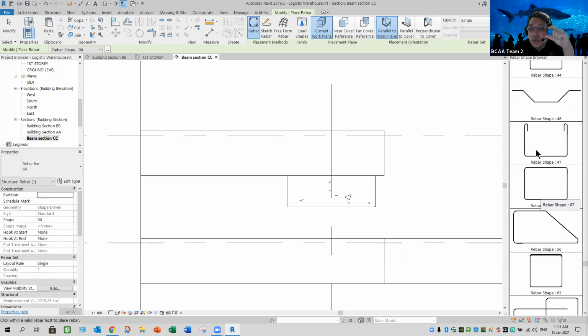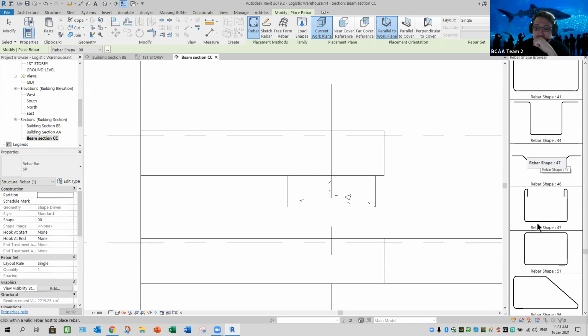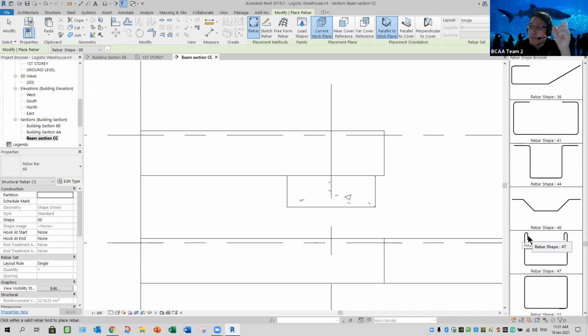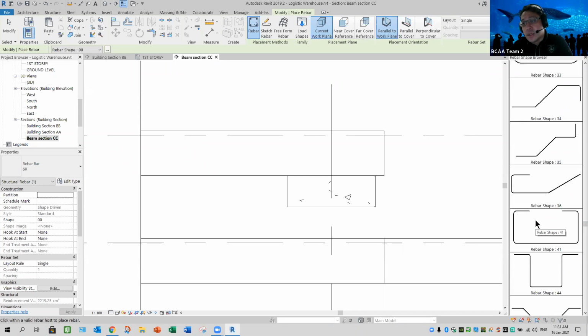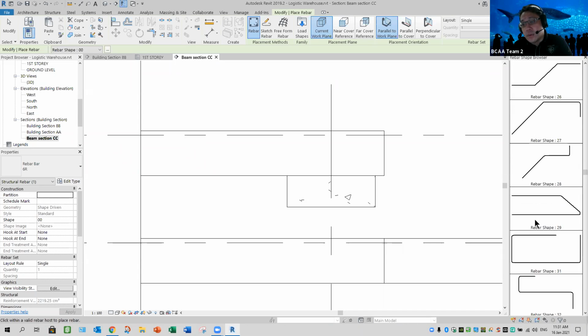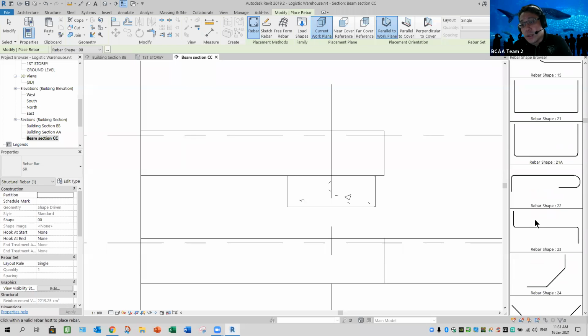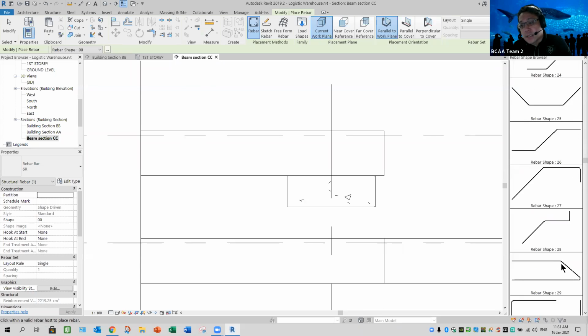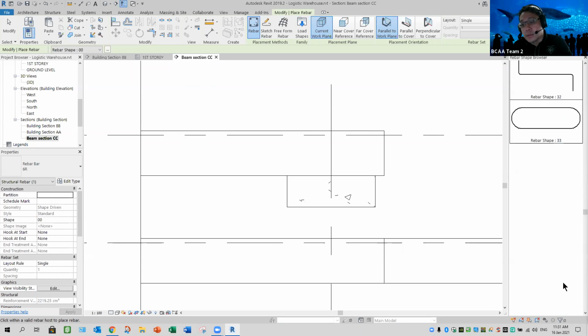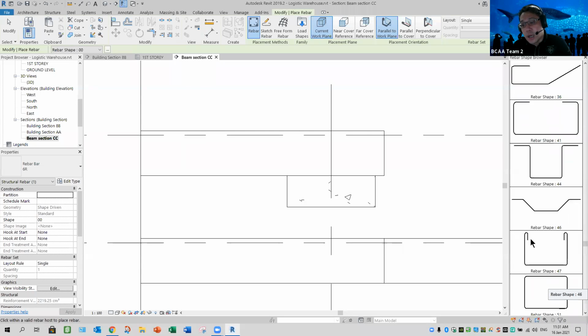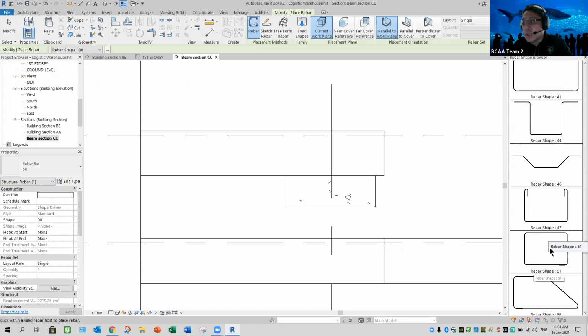So just now the error message is asking whether your rebar is supposed to behave like this. There's a bend hook angle, which is like 135, 180 or 90 degrees. But you can see the rebar default, the 51, where is it? It doesn't have a hook bend angle, so they actually enclose nicely.